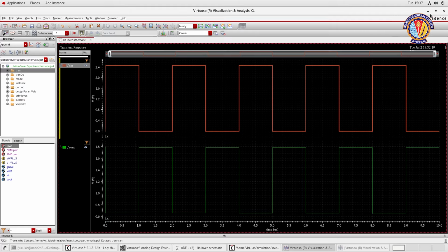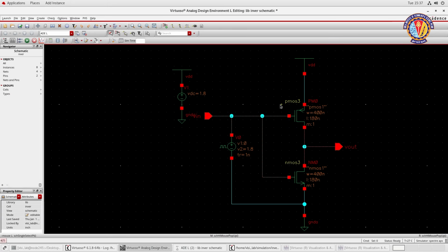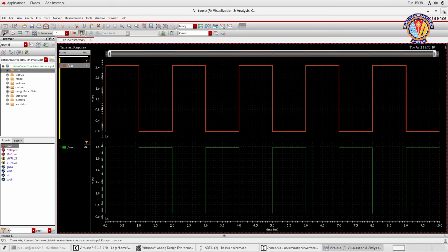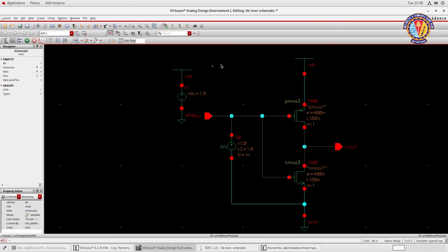So now we designed a CMOS inverter. Then for that inverter, we have measured the power and delay. So power was something in the 14 nanowatts and delay had two components, which was 75 picosecond and the other was 50 picosecond. Then by using mathematical calculations, we can find the average propagation delay, right? So now moving into the last part where we are going to create a symbol.